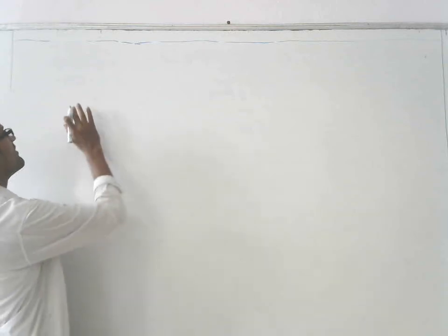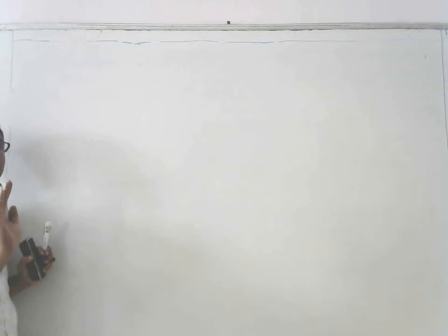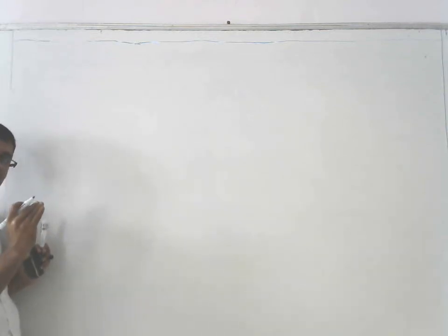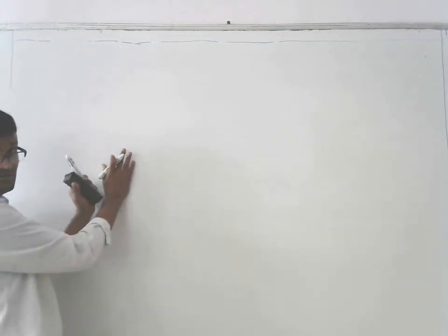We have the receiving end voltage and receiving end current, and we have to calculate the sending end voltage and sending end current. For that we have to apply Kirchhoff's laws, KVL and KCL. But because of load variations, writing KVL and KCL is very difficult. That's why we define the transmission line with ABCD parameters. The reason we will see in depth. First, let me explain how to define ABCD parameters for a transmission line.